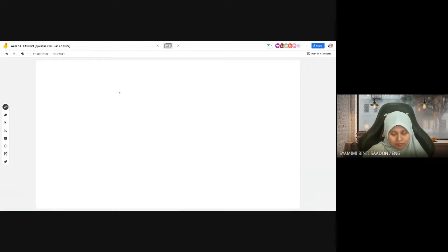Okay, remember the diffuser. Energy balance for the diffuser. No heat exchange, no work output, no work input. For the diffuser, you don't need work and you don't produce work. All of these are in the previous chapter's lecture slides. And then there is enthalpy, of course. There is kinetic energy because we are decelerating the air. So there is a change in kinetic energy, but there is no potential energy or very, very small potential energy, so we neglect that. So we only have enthalpy and kinetic energy.